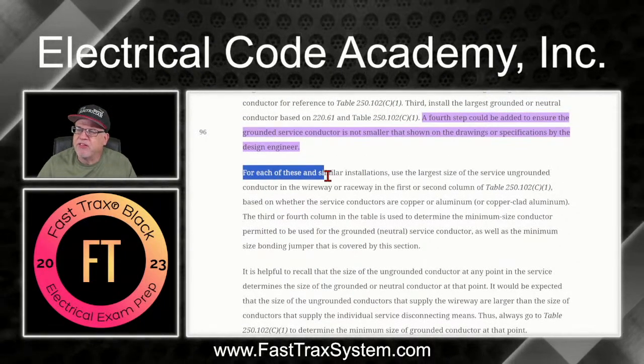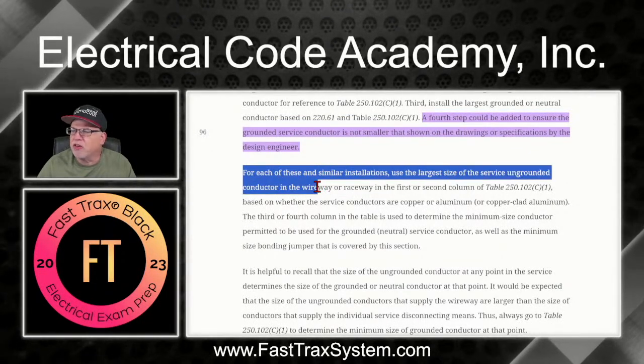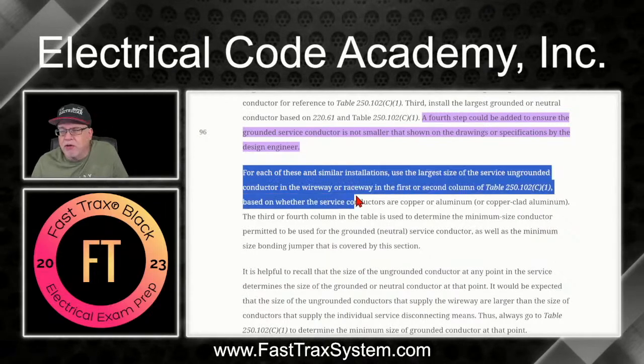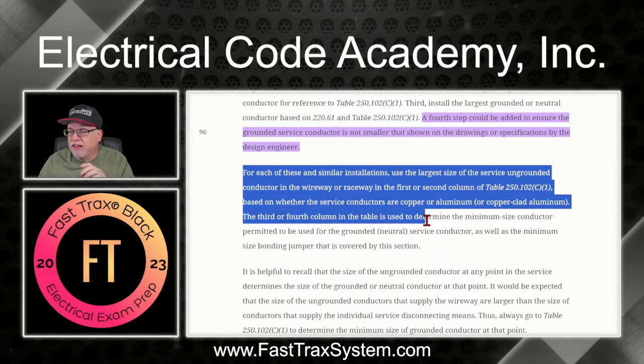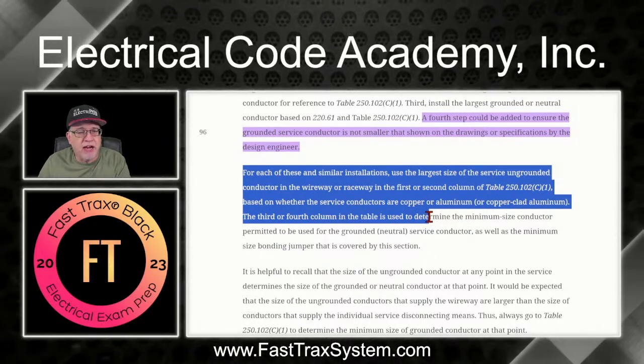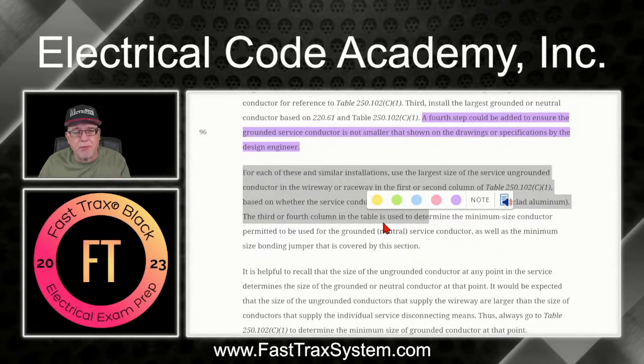So for each of these similar installations, the use of the largest size of the service ungrounded conductor in the wireway or raceway, in the first or second column we looked at, that was what told you the copper or aluminum columns. And then, of course, the sizing of the grounded conductor is in column 3 and column 4, based on whether or not it's copper or aluminum.